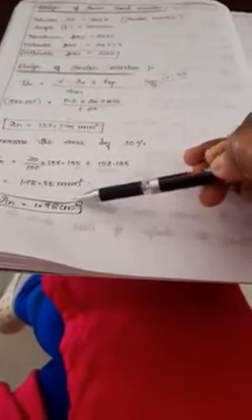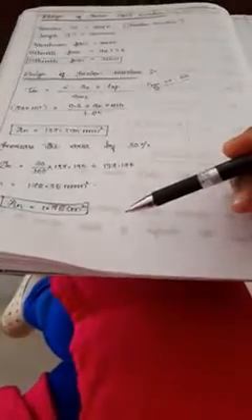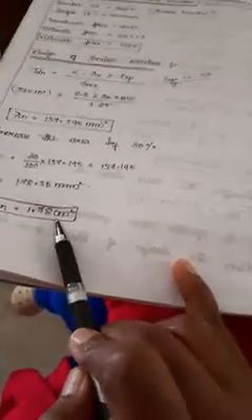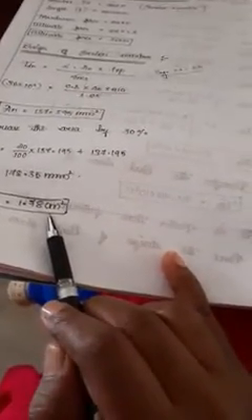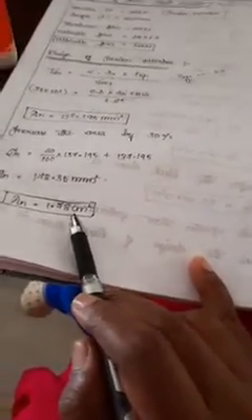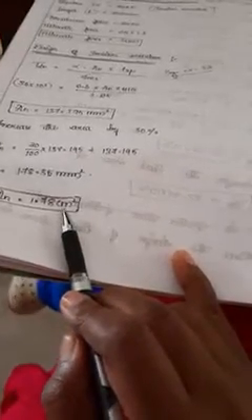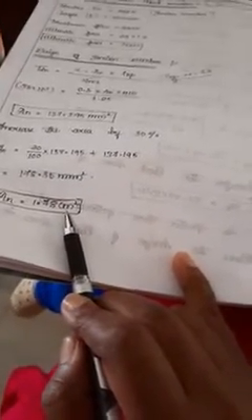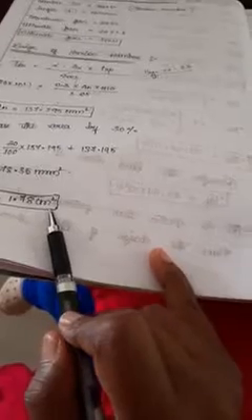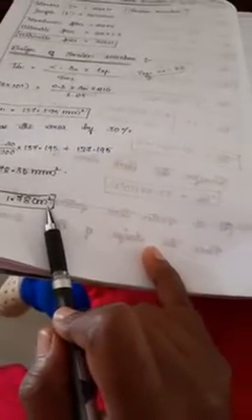So how do you select an angle? I already told you, for the bottom chord and top chord member you select a double angle, whereas for the inner chord member, based on this area, you need to select a single angle. From the steel table, select the equal angle nearest to this value. For the safer side, always select equal angles only.